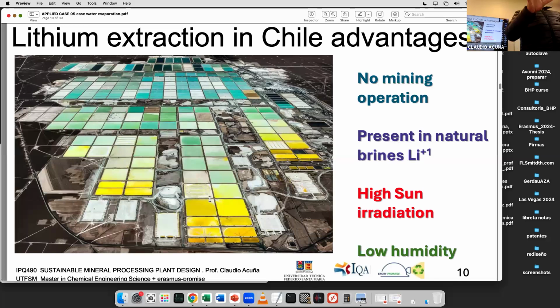Capex for 0.2% lithium is 30%. Let's say in a project, it's a lot of capex, but in the case of Argentina, it can be 50%, because as you reduce the concentration in the original, you need more ponds. So having 50% investment, and you have a lot of losses because you have a kind of carpet, HDPE. When you remove the salt, you cut it and you lose a lot of solution. So it's good for the condition, it's cheap operating condition, but it's not that cheap in terms of investment.